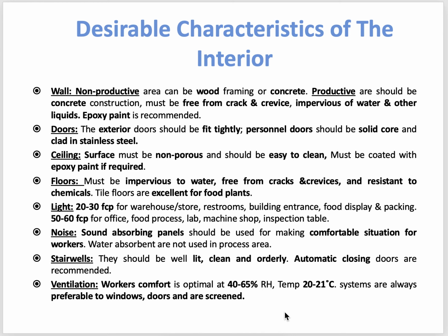It's not good to be in a very low relative humidity environment. So the most comfortable range of relative humidity is 40 to 65%. Temperature of 20 to 21 degrees Celsius is comfortable.